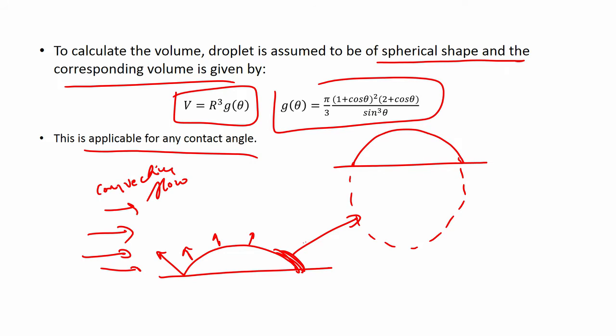So what that flow will do is that it will go over the droplet, right. So it will basically dislodge this saturation water vapor that is accumulating near the droplet surface. So actually a fresh stock of air would be brought in. As a result of that, you can expect an increase in the J flux. That is because simply you are not bound by diffusion anymore.